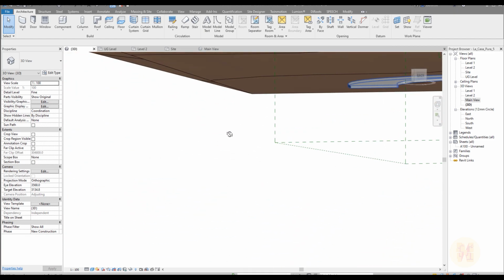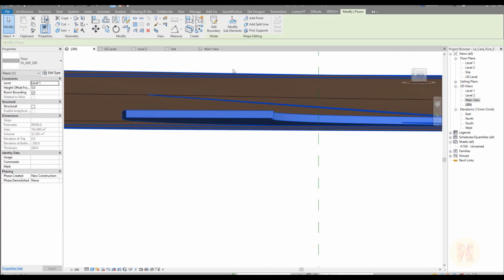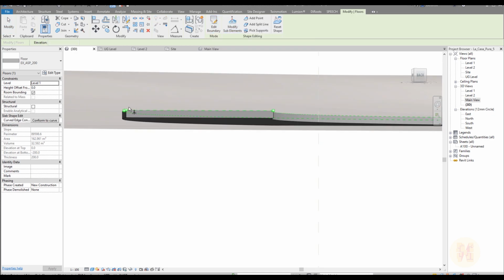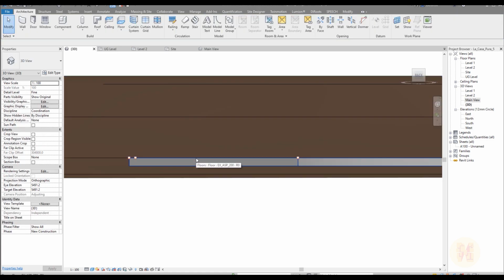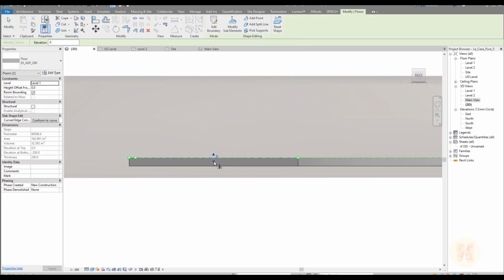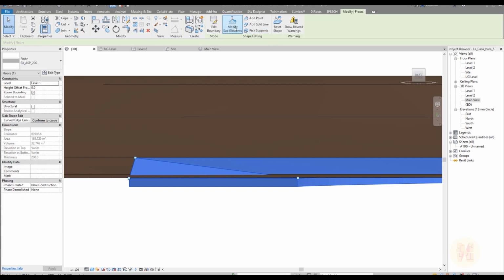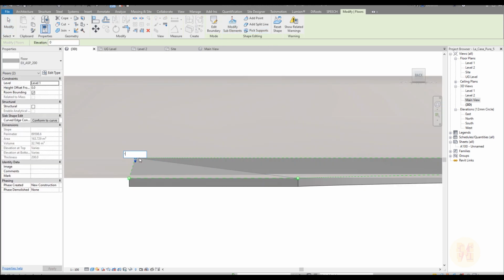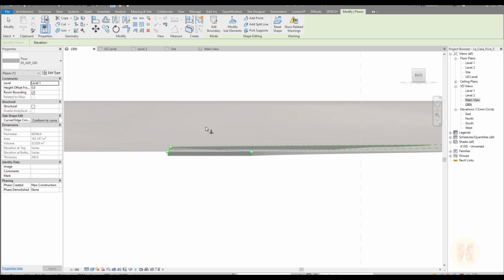Actually, as you can see, here the distance is actually not right. I mean the height. You should go to the modify element, select these two elements and let's make it down. Let's make these elements a bit lower. I will use this line and I will say it will go till here. Why not? And this one, oh, it's always like this. And this one will be minus 150. It's not enough. Minus 250. Yeah, maybe minus 260. Yes, much better.